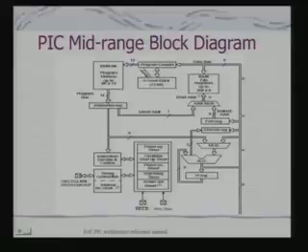I have got this program counter, and program counter is obviously generating addresses for my program memory for execution of the instruction. The interesting feature is it has got a hardware stack. Why is the hardware stack there? Because when there is a call or there is an interrupt, the program counter value has to be saved to enable return to that same location.